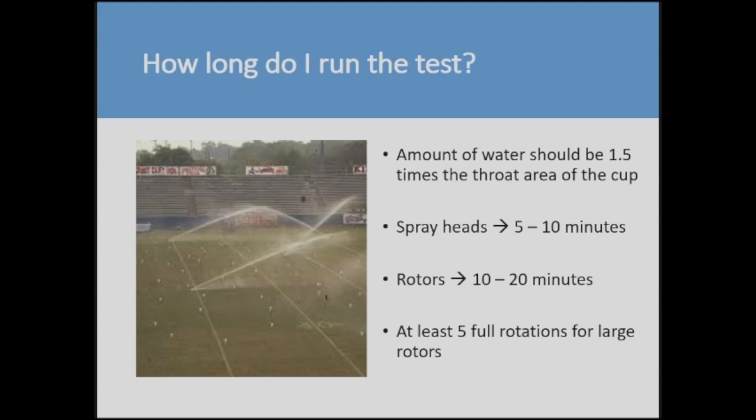Usually that ends up being about 5 to 10 minutes on a spray head, maybe 10 to 20 on a rotor type. So for most of y'all's fields, we're looking in between 10 and 20 minutes, but that depends on your field. If you've got a really high precipitation rate, you may not need to go that full allotment. But when I run a test for rotors, usually 15 minutes is a good starting point. And then if I feel like there's not enough water in the cup to be confident in what I'm measuring, then I might bump it up and try it again. There's no reason you can't do a couple of these, to feel like you have confident information in your test.